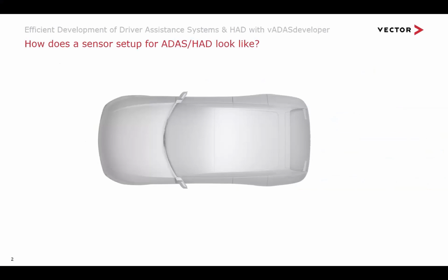How does a typical sensor setup for ADAS or HAD look today? What we see very often are setups that contain a front radar coming from ACCs, being extended with a front cam. Those two sensors are very often used for AEB systems.